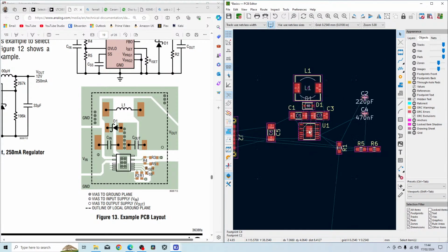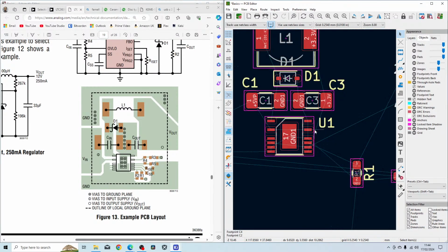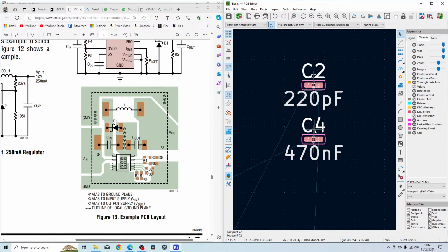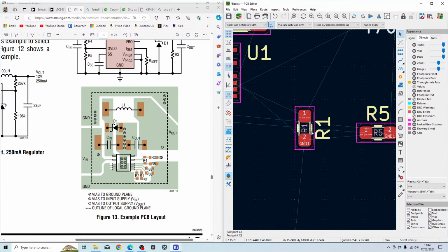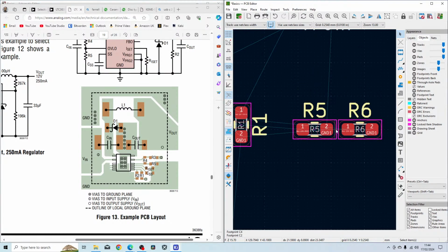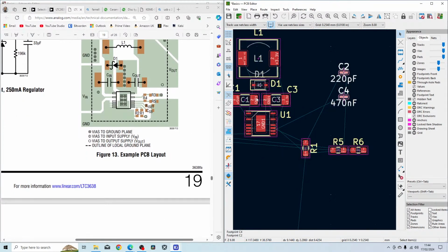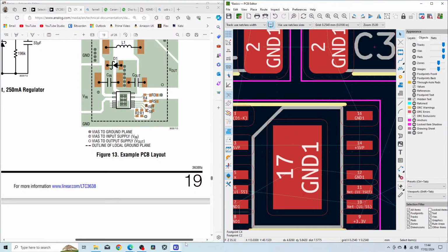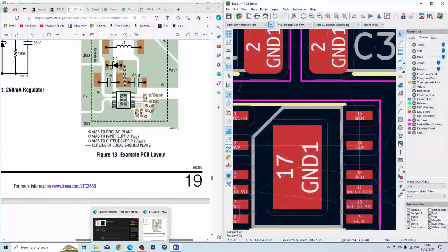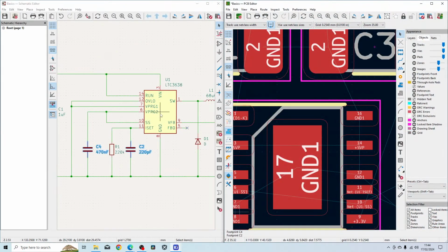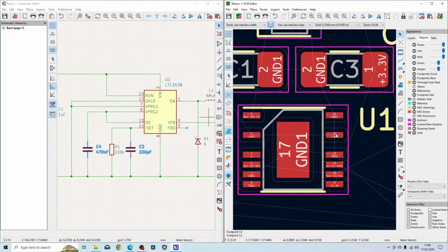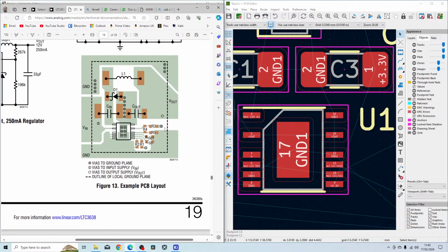So this is going to 5VP. So those are two capacitors. I want to find the resistor that's going to 5VP. Oh, it's not going to 5VP. Pin 14. Have I made a mistake on my schematic? Something doesn't match up. I don't actually have pin 14 going to run. Okay, so obviously this design is slightly different.